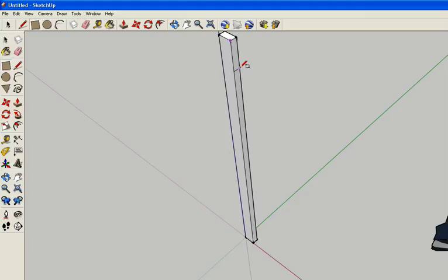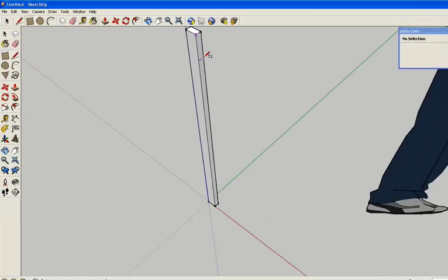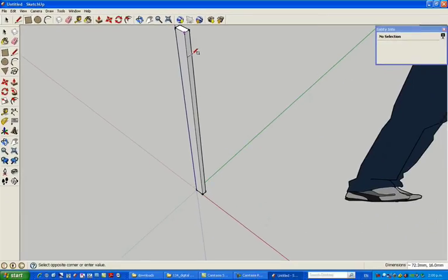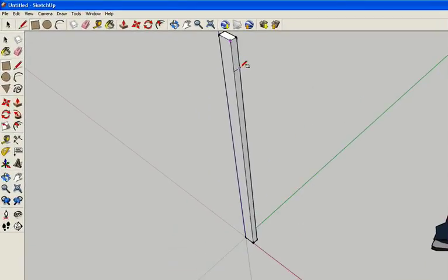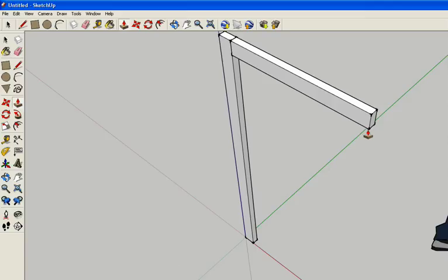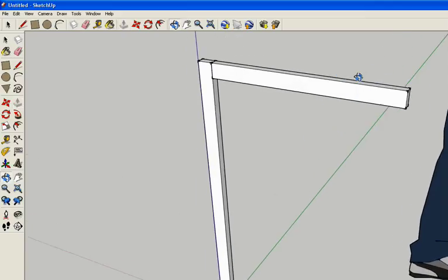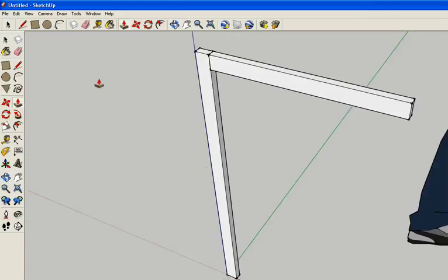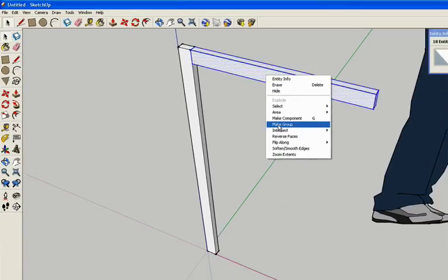And again, down in the bottom corner there under dimensions, we can type in, so we can go 32, 16, and then that way they're going to line up. So we can see we've got another little thing there. So if we pull that out, we want it to be 400, so we just pull it in the direction, and then we can just type in 400, return or enter, and now we've got another piece. So now we're starting to get a shape, and again recommend triple clicking and making that a group.